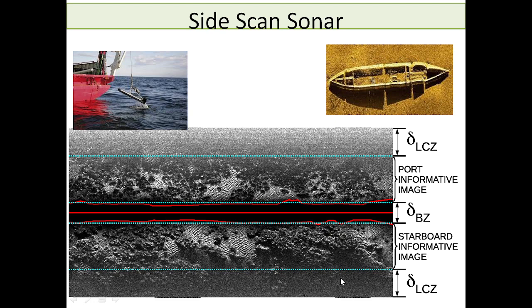Then the side scan sonars. We used them normally to find out cracks or some damages on the concrete structure on the dam wall. This is the sensor that is used to see a photographic view of the bed on both sides.